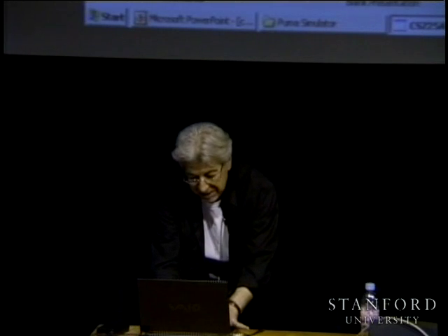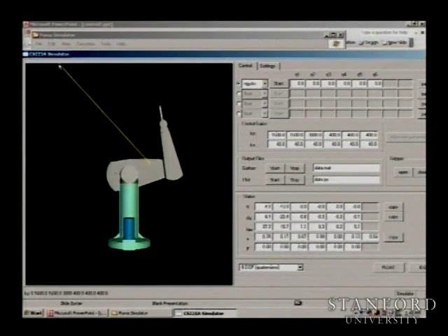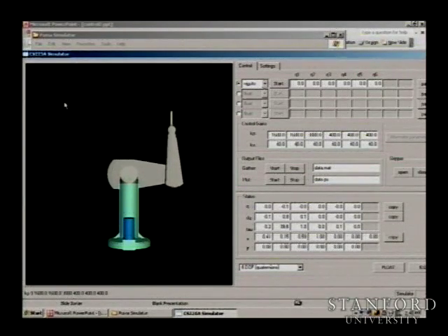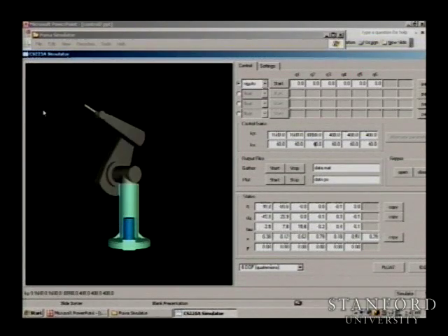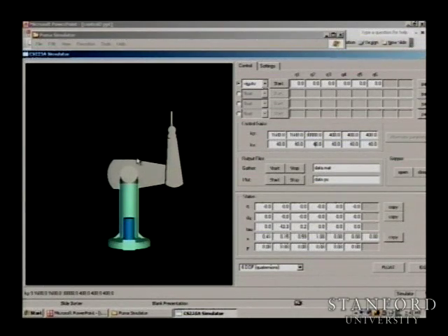Well, then should we keep increasing it? I don't know. We can try. So what is the limit? Let's make it 3000. Now joint 3 is locked. It's not moving anymore. Should we make it more? Okay. So what's going to happen? It's not moving anymore. Now the problem is, if this was a real robot, would 30,000 work? Why? Your motor is going to saturate at some level.